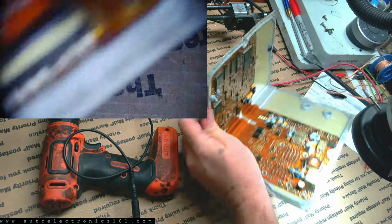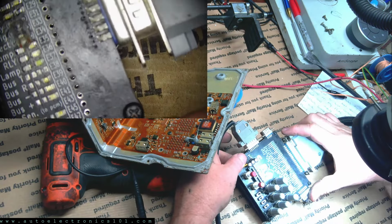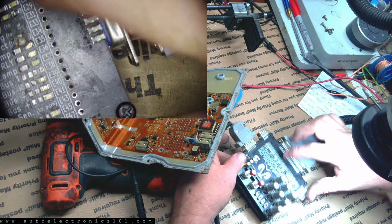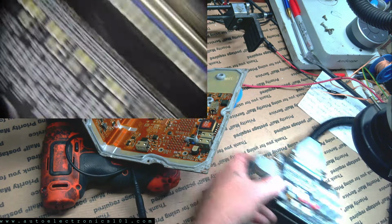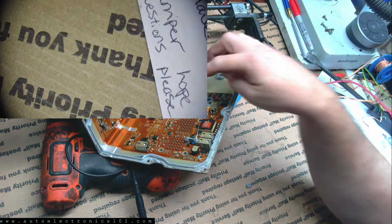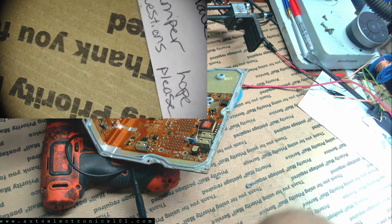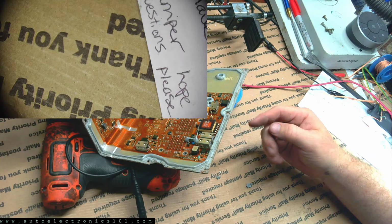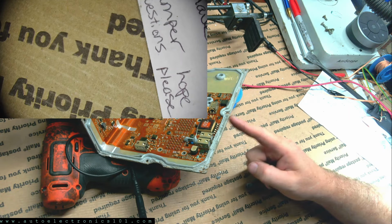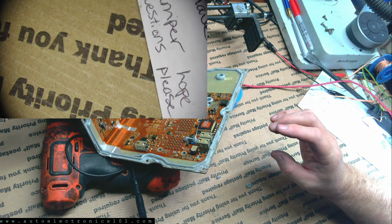I don't remember, but let's see if it's on the tester here, because I do have them named, and there is no E4 on here. You know what? I bet you it is a sensor ground. I bet you that's what it is. I bet you that's a sensor ground coming from the ground plane going to the output, because sensor grounds are about the only thing that I did not put on my tester. And then that would make sense to why everything is working on my tester and not the ECU, because I tie all the grounds together in my tester simulator.